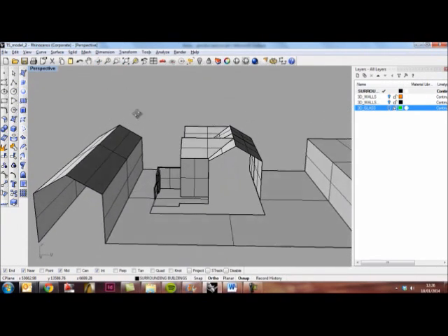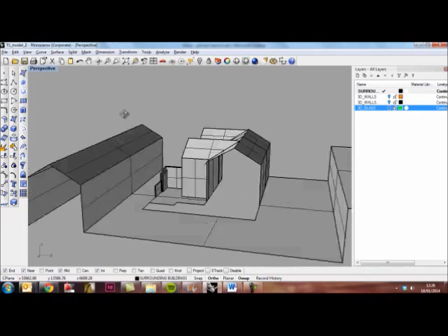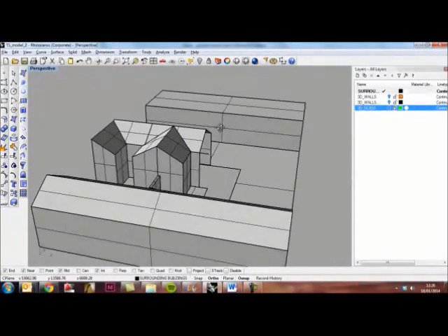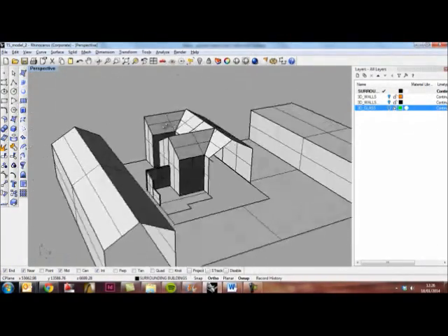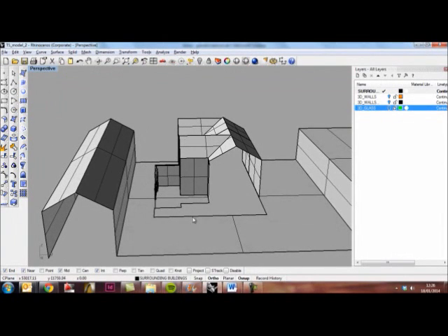I've built the surrounding buildings to a level of detail which I believe to be necessary. That means for exercises that we'll be doing looking at the sun or shadows or the relation of buildings to my building, I've just drawn those buildings which do actually have a direct relationship: those in front of me, those behind me, and those to the left of me. I think I've done that to a level of detail which is no more than massing. I've then made separate layers, and you should do the same. So surrounding buildings was one layer.